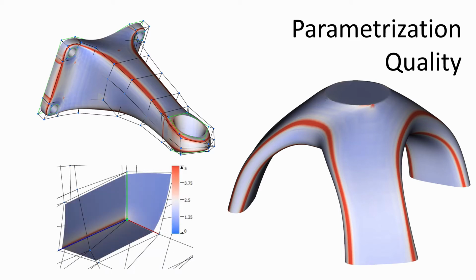While the parametrization is distorted around extraordinary edges and vertices, singularities occur especially at the boundary, or more specifically at boundary edges where two boundary faces meet in a single cell. This leads to the determinant of the Jacobian becoming zero and the mapping Fc losing its injectivity, resulting in numerical instabilities and inaccurate results when solving a given simulation problem.